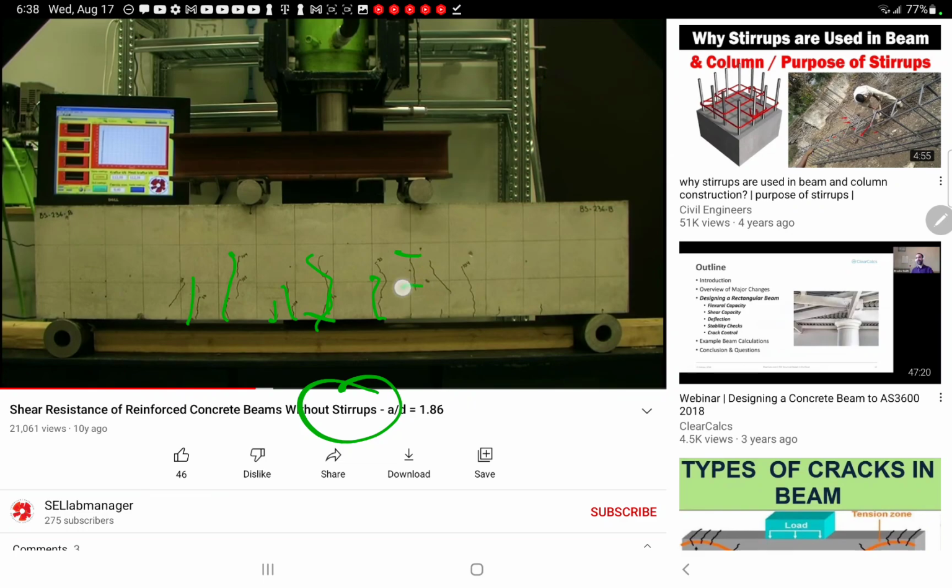Think of it as the neutral axis, what's left of the windshield. And you can profile what's left of the windshield like that. This is what's taking on the loads. The crack is no longer taking on the loads. In this case, though, the exception is it can bridge the crack because of steel stirrups. Because of steel, it can bridge the cracks. Nevertheless, even though it's bridging, we still have the windshield effect going on of how this is working.